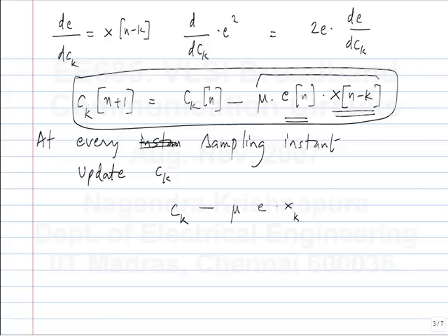But how do we implement this part? What do we need to implement that? So, you need to generate the product, that's the bottom line, right? You need to multiply x with E. How do we do that? What are possible ways of doing this? Basically, we need a new block that we have not used before. So, we need to be able to multiply the signal with the error. Yeah, so some implementation of an analog multiplier, that's what you are suggesting. Yeah, that is doable. Some implementation can be based on the difference of squares, or it can be based on exponentials or logs. Okay, so that's the analog way.